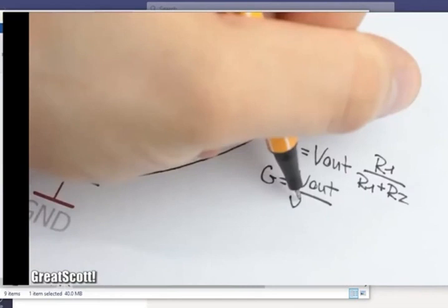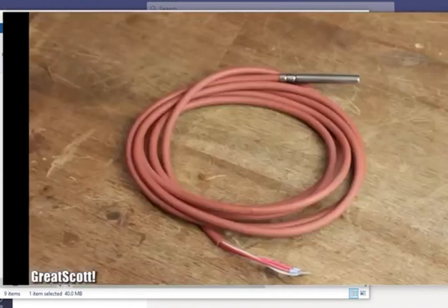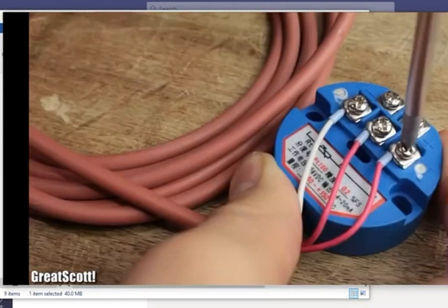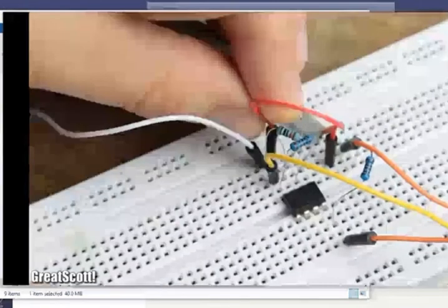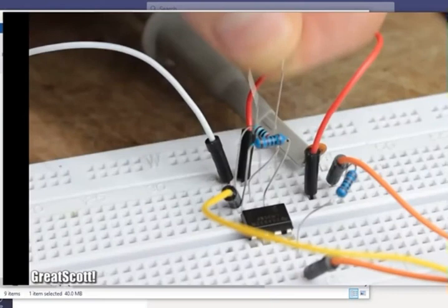Such a circuit can be used to amplify the signal from a sensor, like for example a PT100 temperature sensor, or the AC signal from an electret microphone. This one creates maximum voltage peaks of around 100 millivolts AC, which I can now easily amplify with a gain of 48 by changing the 5.1 kilo ohm resistor to 47 kilo ohm.